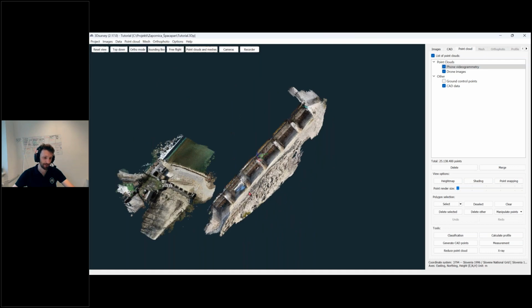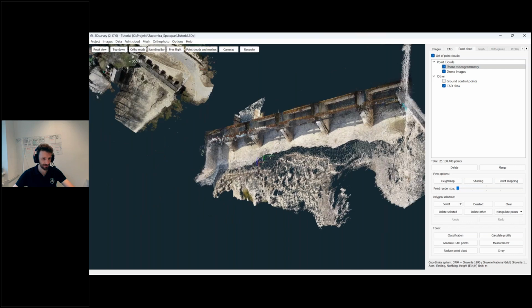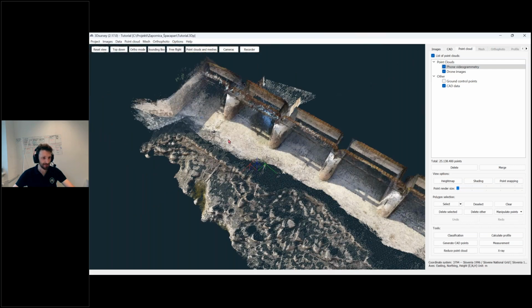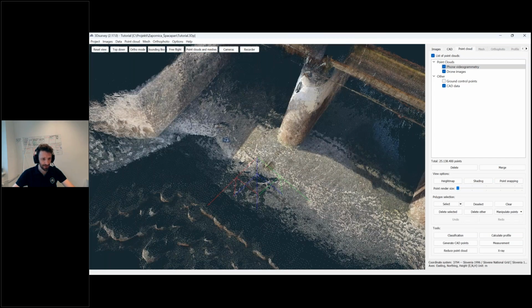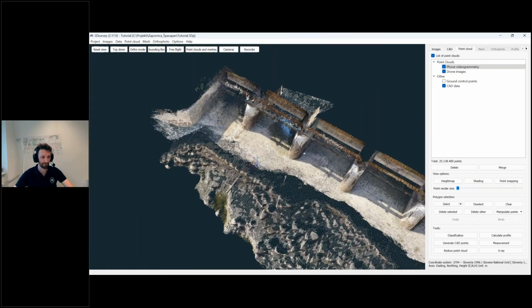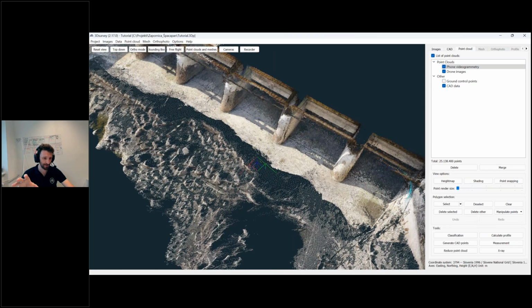So one thing we can do is use our ground control points. It's not necessary, it's just the best practice and probably the easiest one. We can map them in 3Dsurvey. We click on them and make them CAD points, and then we align those points on point cloud 1 and on point cloud 2, and they will fit together.